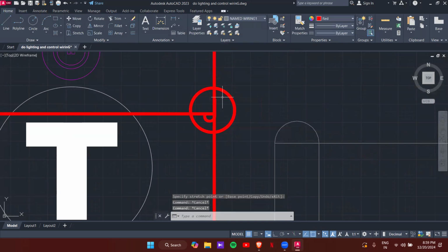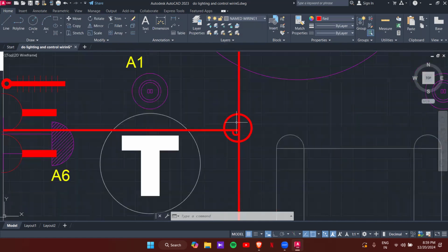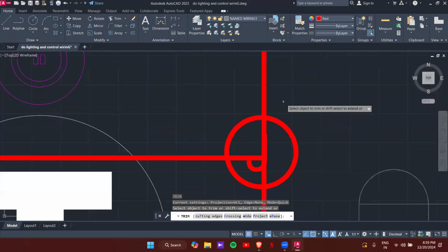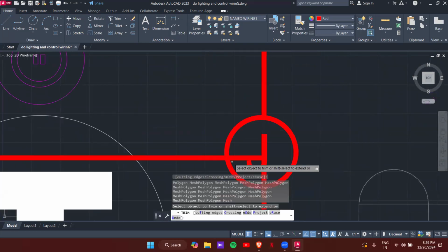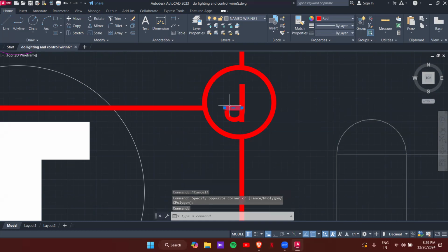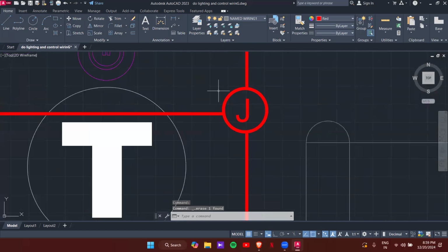Now, once you place the junction box, the first thing to notice is that wherever we are taking an intersection or a branch, over there we have to place one junction box. And for the connection of the ceiling components, this one is a ceiling component, all of these are ceiling components, you also have to show a junction box. Using the trim command, you can trim the portion which is extending inside the drawing. Like this you can do it. So that's the junction box.